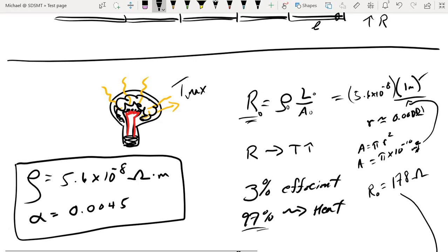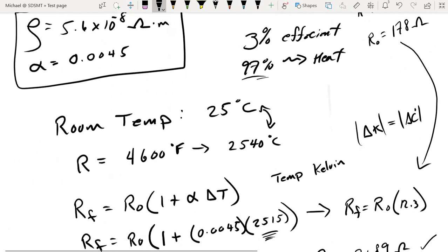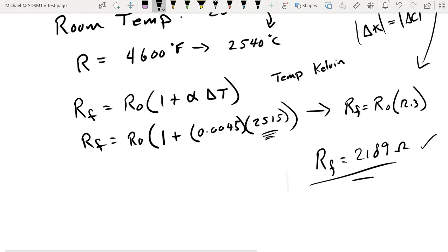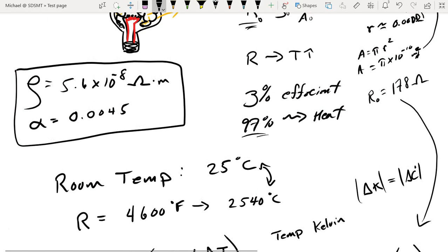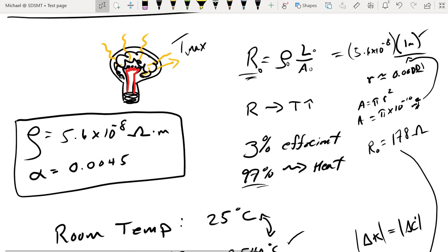In fact, these bulbs should be evacuated. You don't want a lot of gas in there, because as the temperature increases to something approaching the temperature of the surface of the sun, gases inside that bulb would get very hot, they would expand, and the bulb might explode. In addition, you don't want air or anything that has oxygen in there, because that will cause the tungsten filament to oxidize.